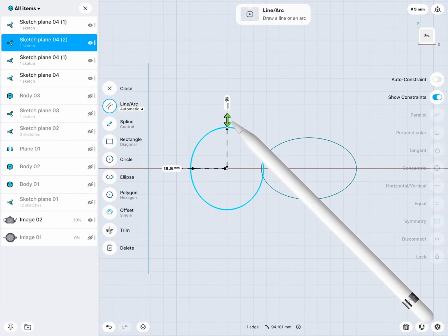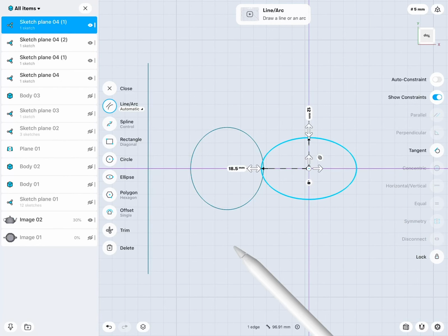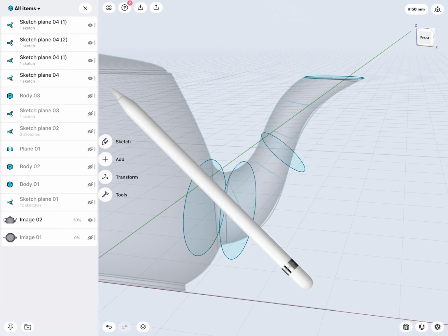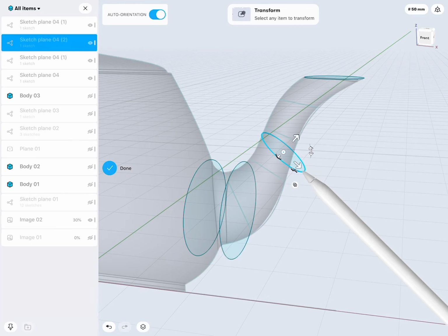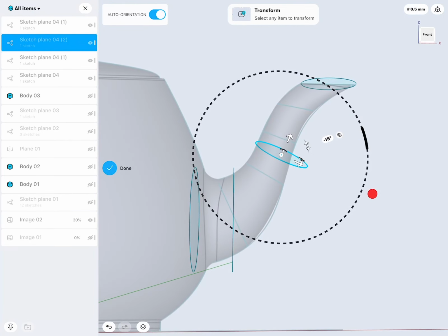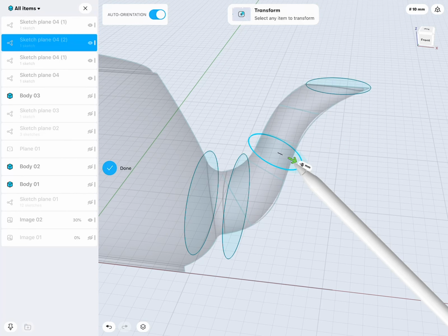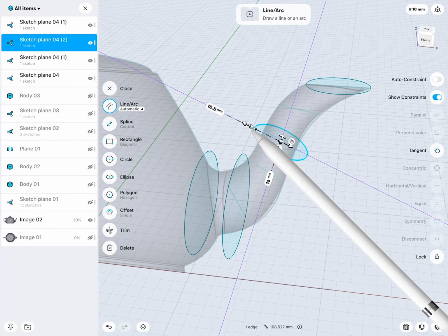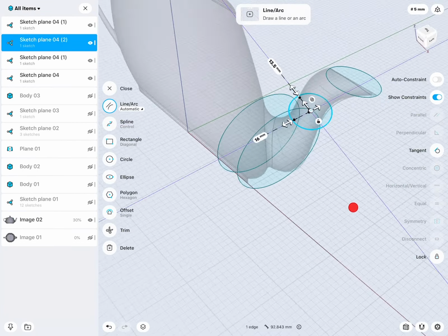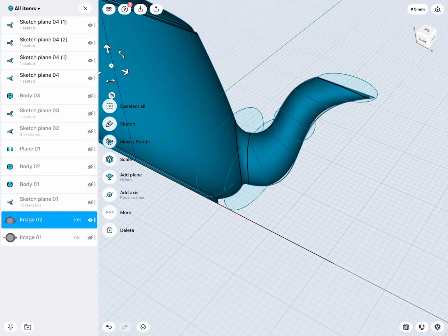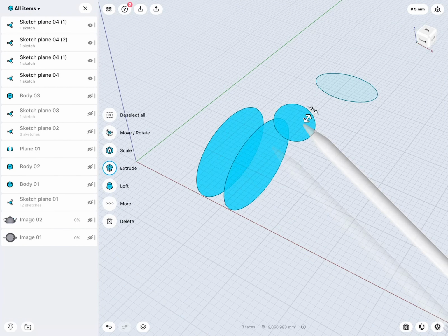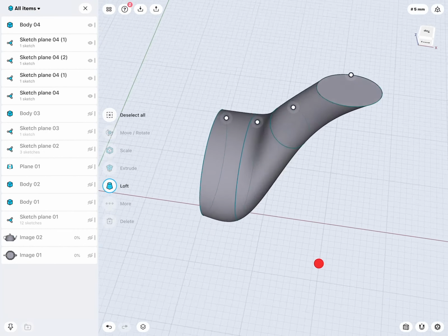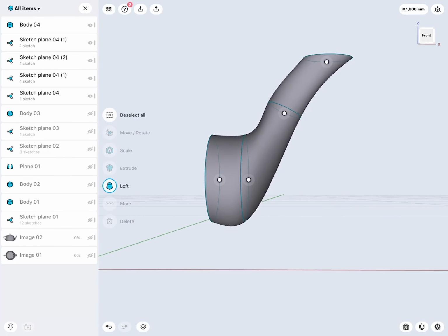Obviously, this one here should be a little bit wider than this one. Let's go back to Transform and Rotate, maybe a little bit more. Okay. Go in, go a little bit there, and change the scaling there that way. Very good. So let's see what will happen now if we select all four profiles and do a loft. There you can see how this actually works. Okay.